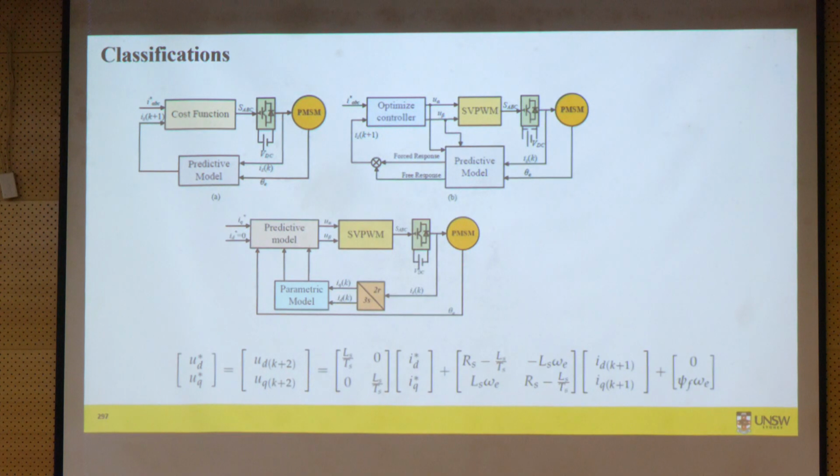That's why, similar to DTFC, sometimes they use SVPWM instead of applying the vectors directly. Find the reference voltages, apply the SVPWM technique, and apply the pulses instead of the vectors.